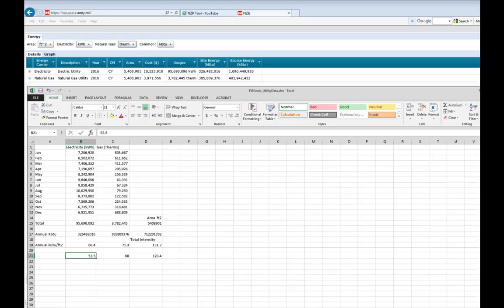When we look forward, I see differences in the weather. It's put together as what's called a typical meteorological year, or TMY. It's made of average years out of 30 years of average data. So the weather file we're getting is automatically different. And then of course there's always model assumptions and model differences, a lot of subtleties. What I look for is to operate within kind of a plus or minus 10%, or on a total, I try to be within kind of like 10 to 20% of the differences.